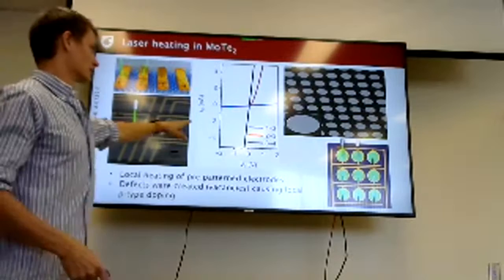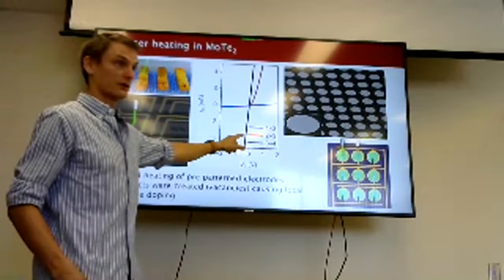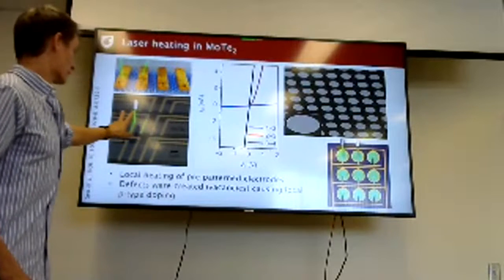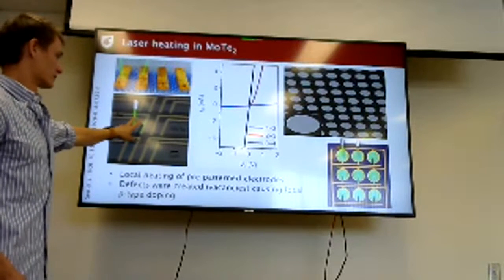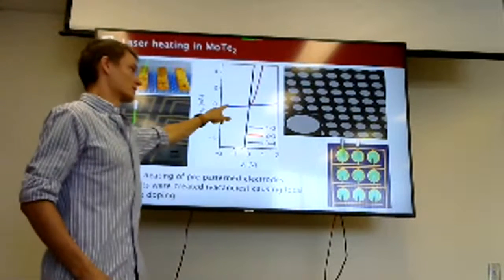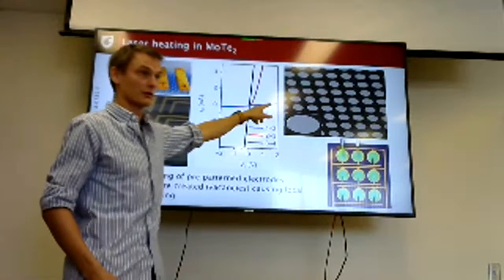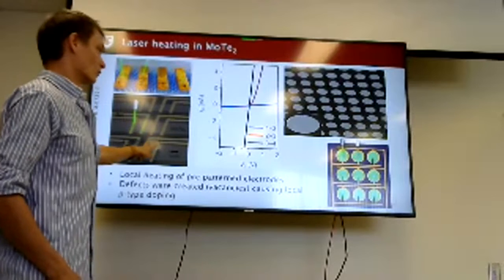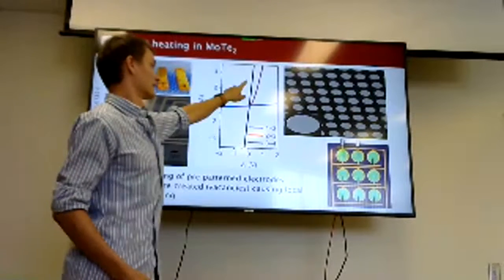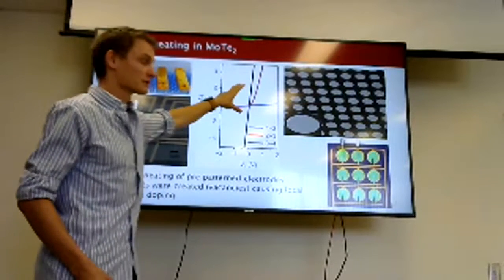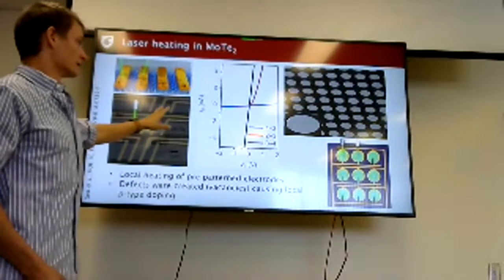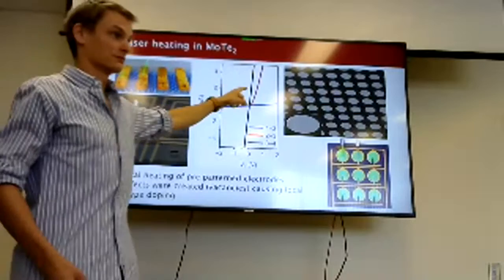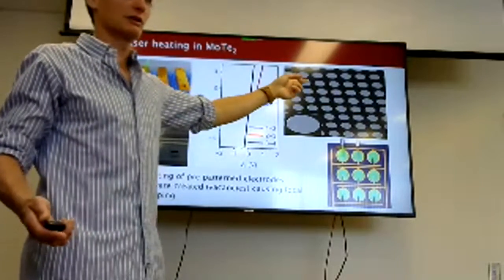And what you can see here is that they got a very good device, where 1 to 2 are the electrodes that have been heated. So there's P doping between them, and the carrier concentration drops dramatically. You get less current flowing. And then 3 to 4 were unmolested, so they have the regular MoTe2 properties. But when you go from 2 to 3, you see a lot of rectifying behavior. And that's a good indication that you made a nice PN junction.